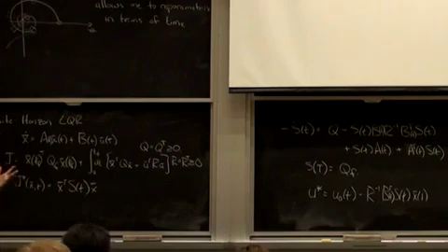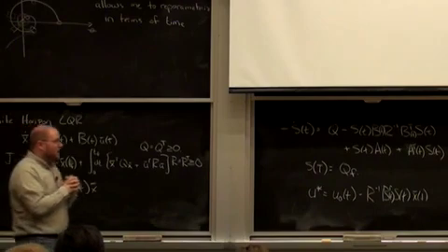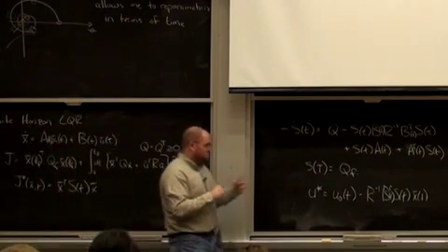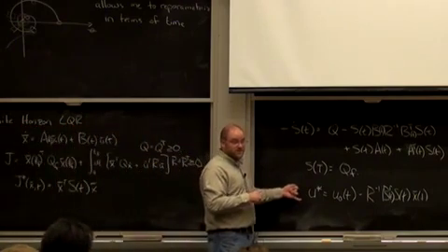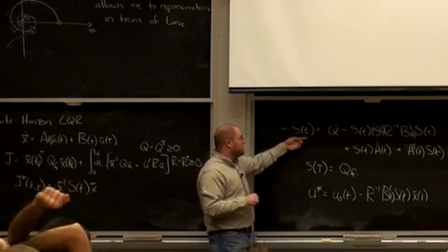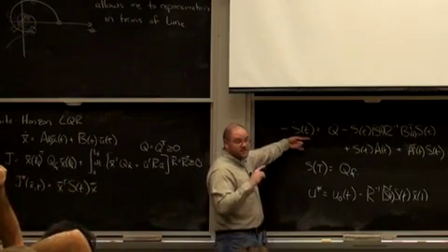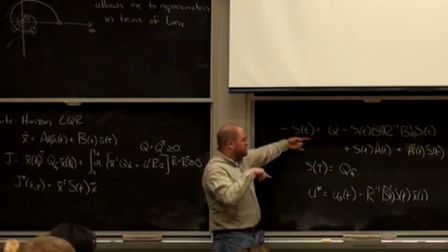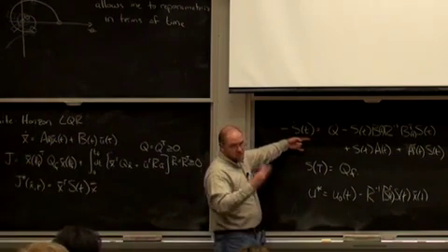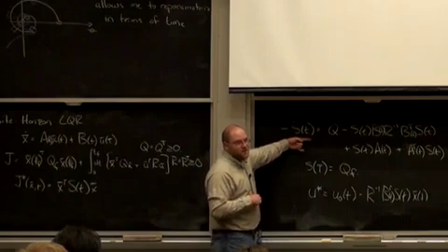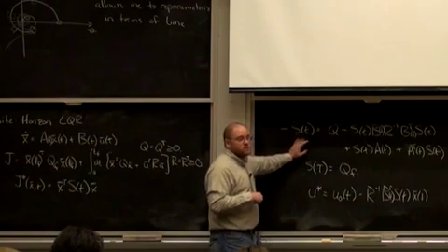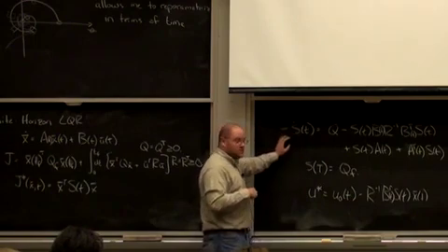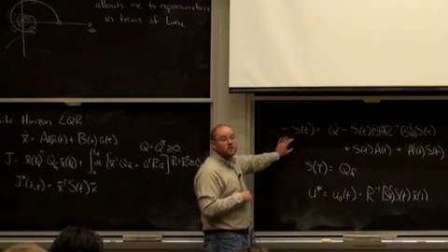If you want to do nonlinear control of a humanoid robot or something like this, this actually scales pretty nicely, right? I just have to solve this equation. S is a matrix that's number of states by number of states, but I could do that in 30 dimensions, that's no problem, right? And even for very nonlinear systems, local linear feedback works very, very well.